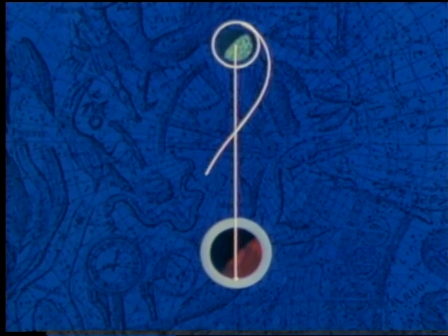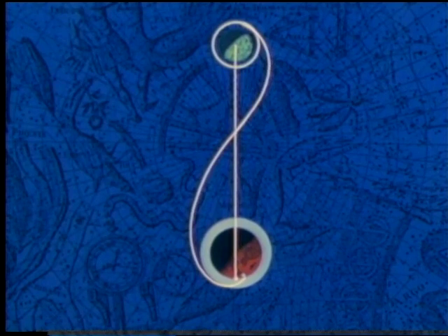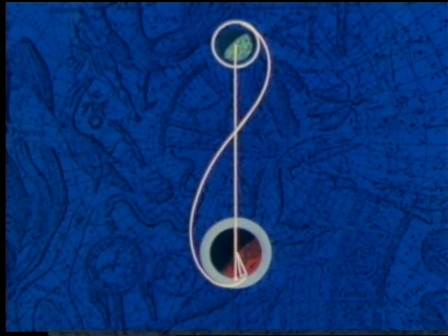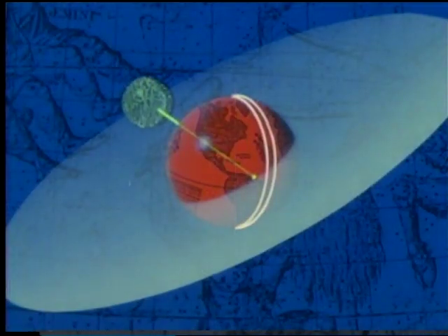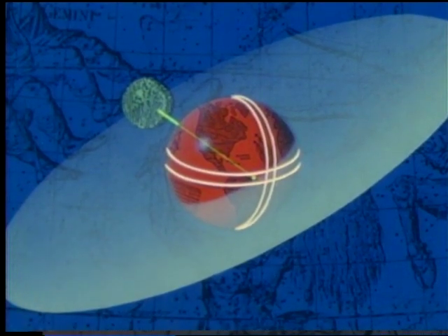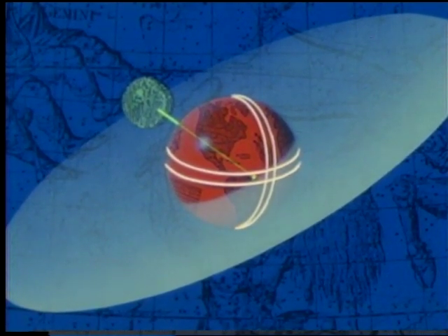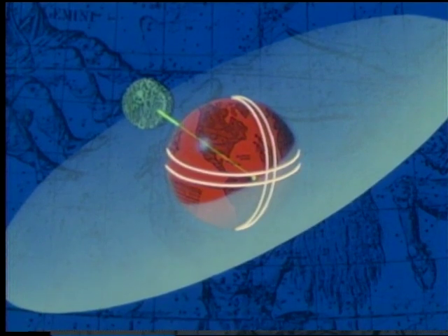In review, we have seen that accurate control of the landing longitude can be achieved by varying the transit time of the returning spacecraft until the Earth and recovery forces have rotated to the desired position. The range of landing latitudes is determined by the range of return trajectory planes and the entry range. The position of this band of landing latitudes, on the other hand, is relatively fixed by the declination of the moon at the time of trans-Earth injection. Thus, control of landing latitudes is extremely limited.